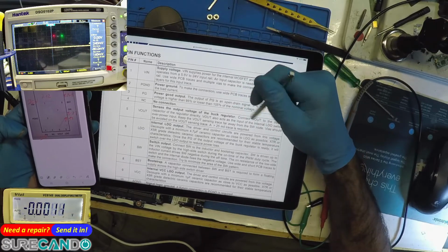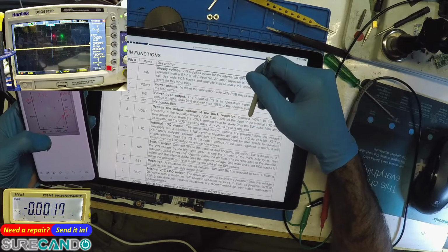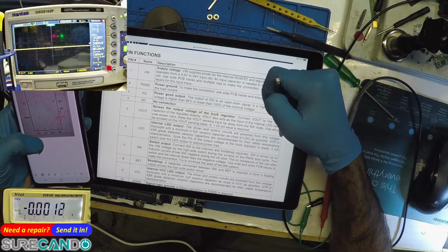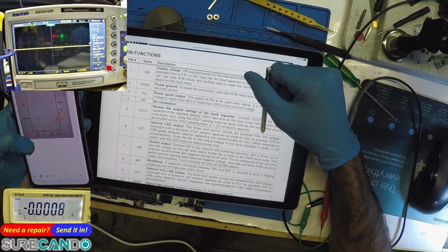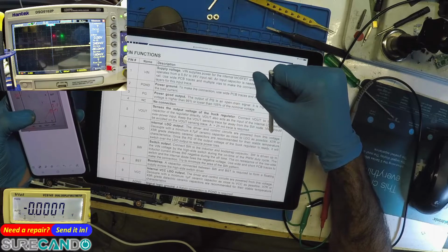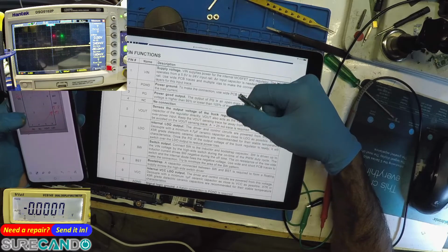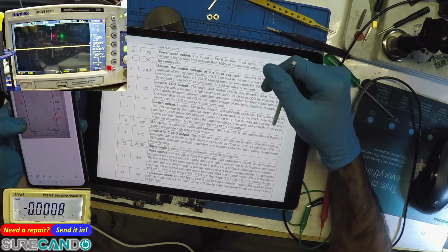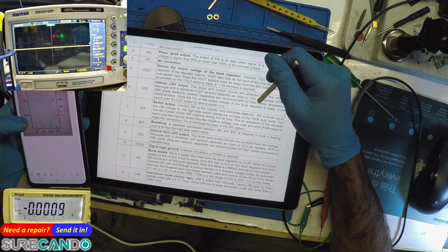Okay, voltage out. Senses the output voltage of the buck regulator. Connect Vout to the output capacitor of the regulator directly. Vout also acts as the input of the LDO switch over power input. Keep the voltage out sensing trace far away from the switch node. Okay. Internal LDO output. The driver and control circuits are powered from this voltage. Decoupled with a minimum 4.7 microfarad ceramic capacitor as close to LDO as possible.